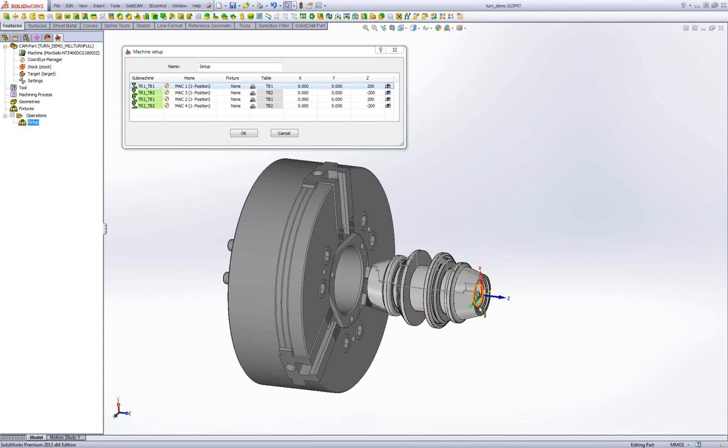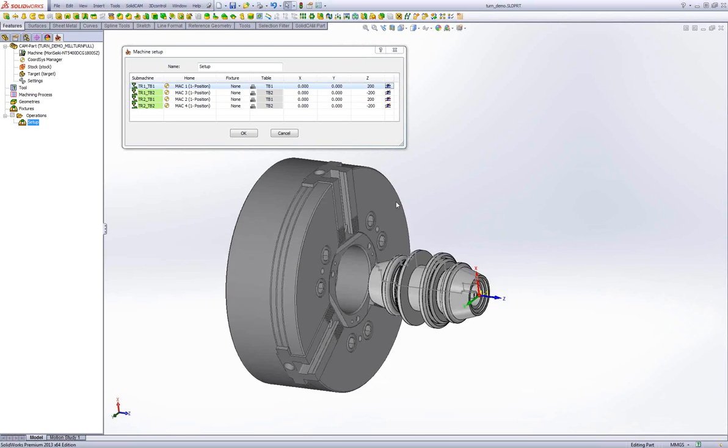In mill turn and turning only Z is important, because we define the coordinate system in center of rotation. X and Y will be 0. In milling parts, we have values also for X and Y. Not always is the coordinate system in center of the part or center of rotation of 4 axis, it can be in a corner of the box. So that's why we have shifts in XYZ in setup. We position the part for each submachine related to the table.